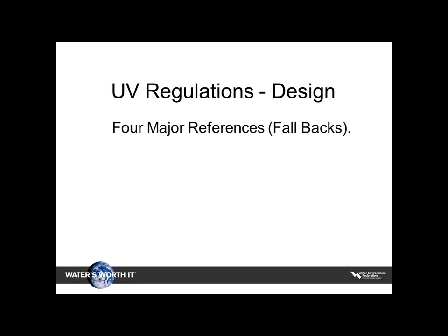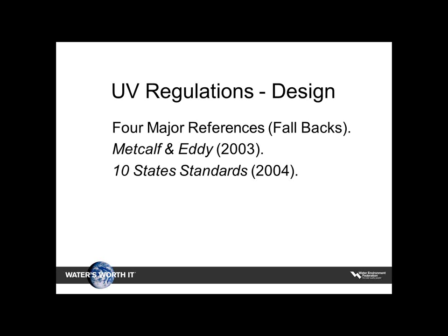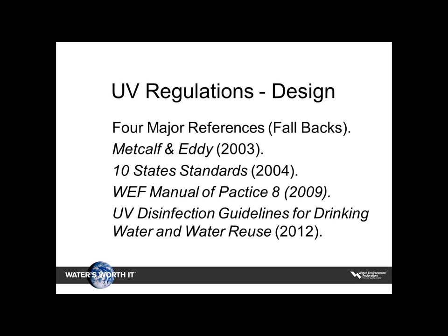So let's talk about some of the design regulations once you get there. If they don't have them in regulations and have written it, there are probably 4 major reference books that most regulatory agencies are going to fall back to. These are the classic fallbacks. Metcalf and Eddy, which is a standard; probably most every review engineer, designer or regulatory agency has a copy of these floating around. Ten State Standards is another one that a lot of people run back to, and particularly regulatory agencies refer to that a lot. MOP 8, Manual of Practice, is another very good one to look at.